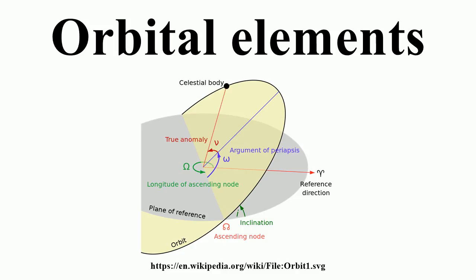The main 2 elements that define the shape and size of the ellipse: eccentricity, semi-major axis. Longitude of the ascending node horizontally orients the ascending node of the ellipse with respect to the reference frame's vernal point, and finally, argument of periapsis defines the orientation of the ellipse in the orbital plane, as an angle measured from the ascending node to the periapsis. Mean anomaly at epoch.